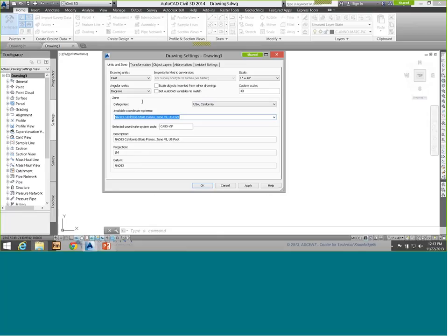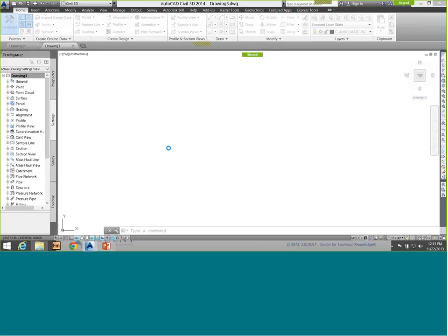If you're constantly working in the same area, let's say you're always working in the state of Utah in the Salt Lake Valley, well, that would be the central zone. And so if I know that I'm always going to be working in the Salt Lake Valley, I can memorize that code, and I could have typed the code in right here and not had to go searching through the categories and then the coordinate systems after that. So I'll click OK, and that's how you can set the coordinate system.